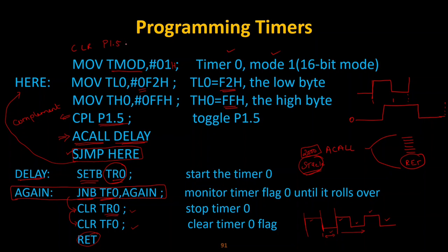You can give this command also, so that it is going to start from 0, and after that one it is going to continue its operation. Like that I can do the programming whatever I want. So here the beauty of this one is that we can create a square wave. Whatever values we give in terms of your count, the width will vary. Even though the width is varying, it is a square pulse, so it always has a 50% duty cycle.